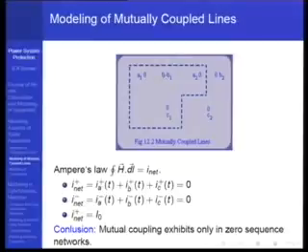Suppose that I only energize circuit 1, A, B, C, with positive sequence currents. Now let's see what flux links the conductor A2. Take a flux path; this dotted path definitely links the conductor A2, because it circles the conductor A2. If this flux linkage is non-zero, then its rate of change will induce a voltage in the conductor A2, and therefore the mutual coupling phenomenon would be seen.